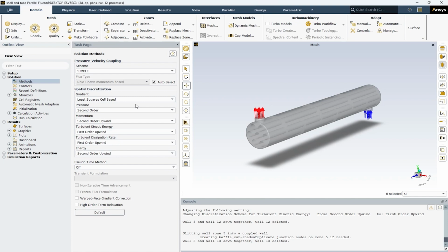The method works by minimizing the sum of the squared differences between the values of the scalar quantity at the cell centers and the values predicted by the linear approximation of the scalar quantity over the entire cell. This method offers a higher level of accuracy compared to other methods like the Green-Gauss cell-based method, especially for unstructured and non-orthogonal meshes. However, it may require more computational resources due to its complexity.